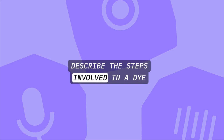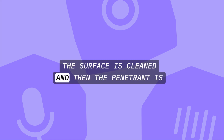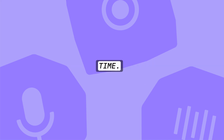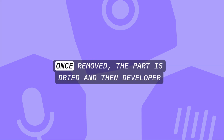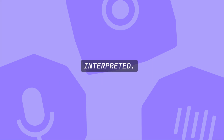Describe the steps involved in a dye penetrant inspection. The surface is cleaned, and then the penetrant is applied and allowed to dwell for a specified time. The penetrant is then removed with emulsifier or cleaner. Once removed, the part is dried, and then developer is applied. The results are then inspected and interpreted.